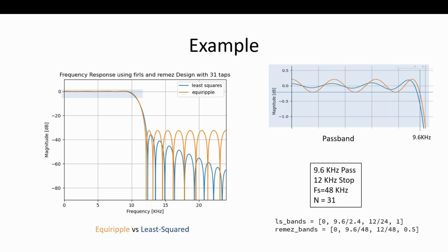And there are, that we're not going to talk about, but there are some uses of FIR filters like in multi-rate processing where you're changing the sampling rate, going to lower rates, where you get this aliasing of all this stuff that's coming out here, right? And the fact that this is going down and keeps going down is really good for those considerations too.